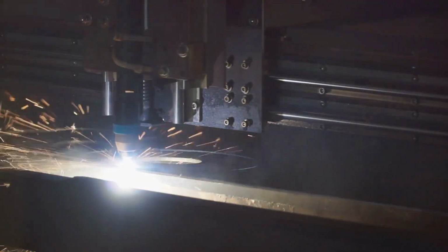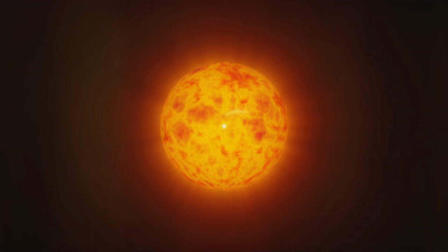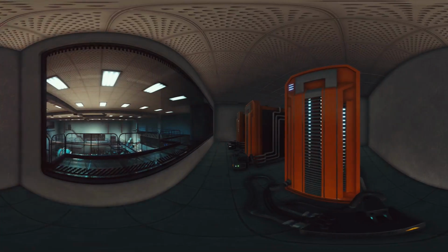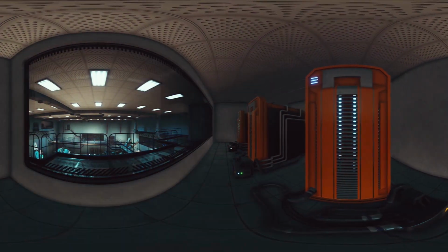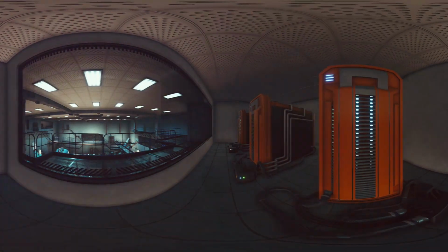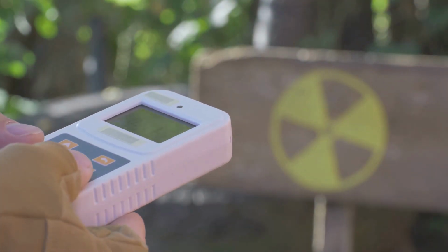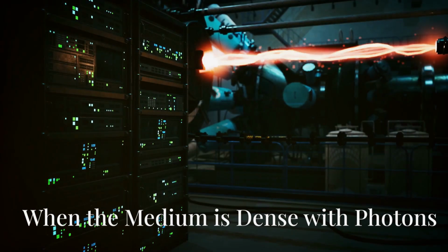However, the P1 model's simplicity comes with limitations. It struggles in situations with highly anisotropic radiation, such as near surfaces or in optically thin media. In such cases, the more computationally expensive DO or DTRM models might be necessary. Despite its limitations, the P1 model remains a valuable tool for obtaining reasonable engineering approximations in computationally demanding simulations. It allows for a quick assessment of radiation effects and can guide further analysis using more sophisticated models.